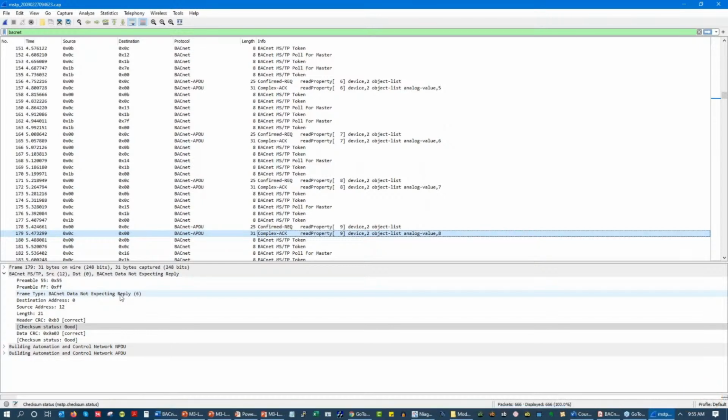That being said, that's the basics of BACnet MSTP, kind of high level. Pretty straightforward, not terribly difficult protocol. A lot of people tend to mess it up because they don't understand the baseline requirements: unique address, unique device ID, same speed, protect your end of lines, only use them at the literal end of line, don't cross the polarity of your wire, and don't change wire types. If you follow those, you will almost never have a BACnet MSTP communication issue.